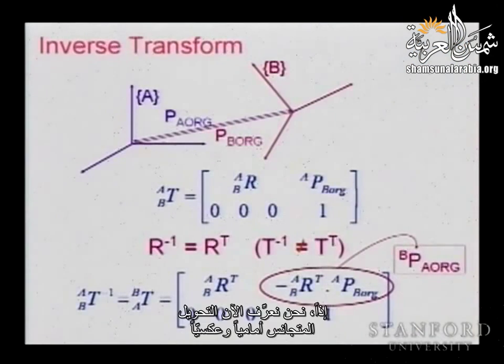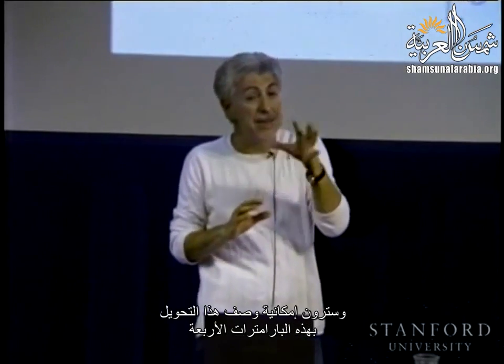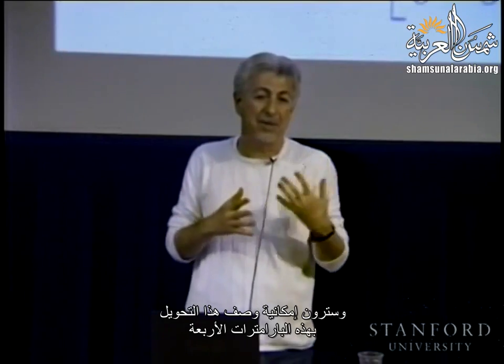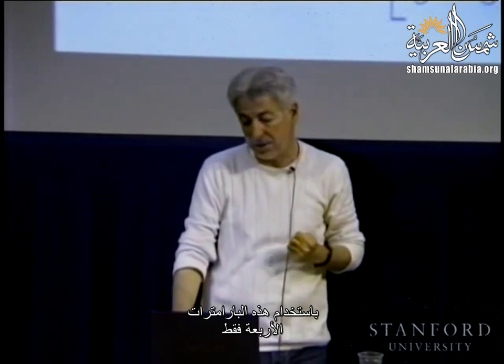Okay? So now we know the forward and the inverse of the homogeneous transformation, and it is going to be essential. We're going to use the homogeneous transformation to describe the kinematic chain of the manipulator, and we will see that this transformation could be described by 4 parameters, the DH parameters. So we will be able to describe each relation between successive links just using 4 parameters, the DH parameters.